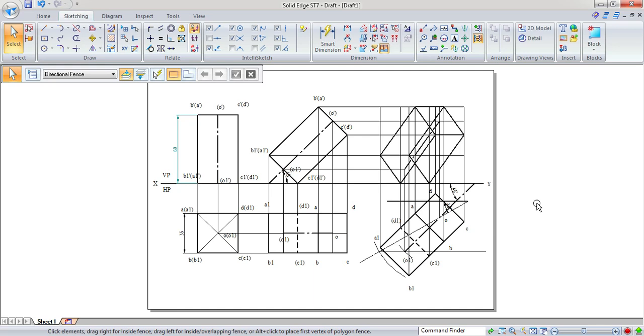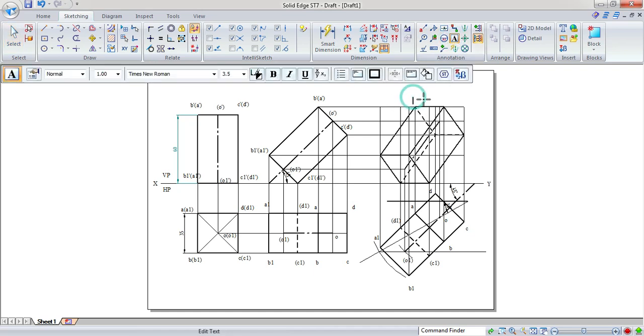Yes. So here, the D corner: when you are looking from the front, that is actually not visible. So that's why the D point will be here, and the edges which are in connection with the D corner are not visible to us when we are looking from the front. That's why you make all these three edges hidden edges. So make hidden edges, then finally you write down the annotations.